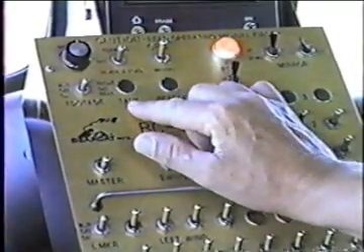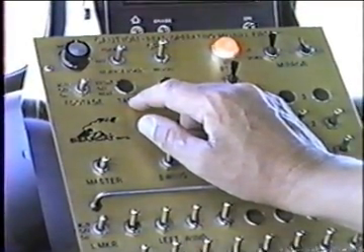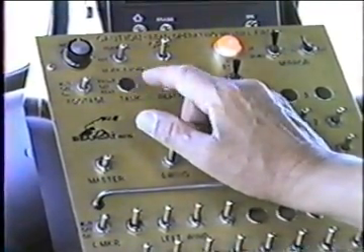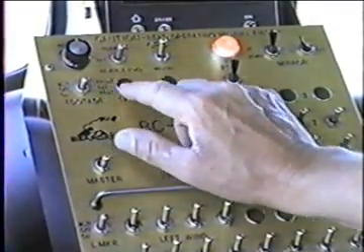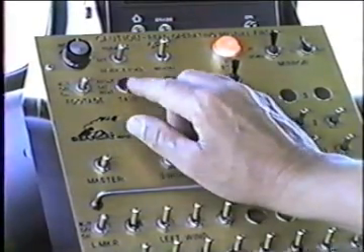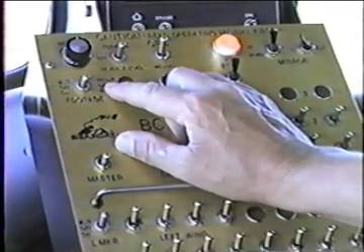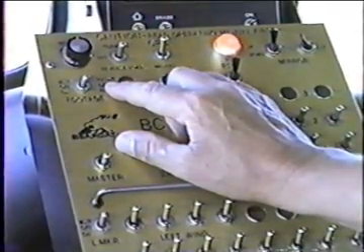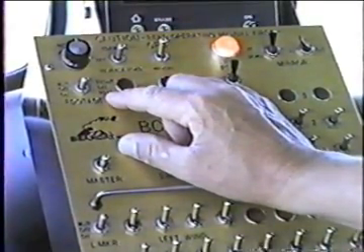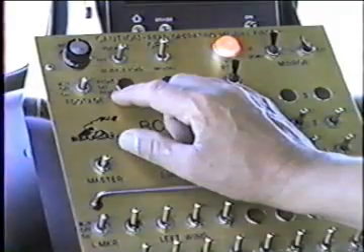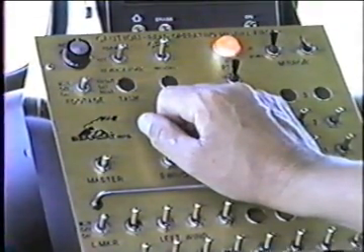This switch would be for a tank valve. If this truck had front suction, then it would probably have remote operated front and rear suction. Switch in the center position, both tank valves would be closed. In the up position, the front tank valve would be open. That's if we were going down a steep hill, spreading and needed to empty the tank out then. In the down position, it would be pumping out of the rear of the tank, the rear tank valve. With a short tank like on this truck, there's no need for the front suction, so this option hasn't been taken.